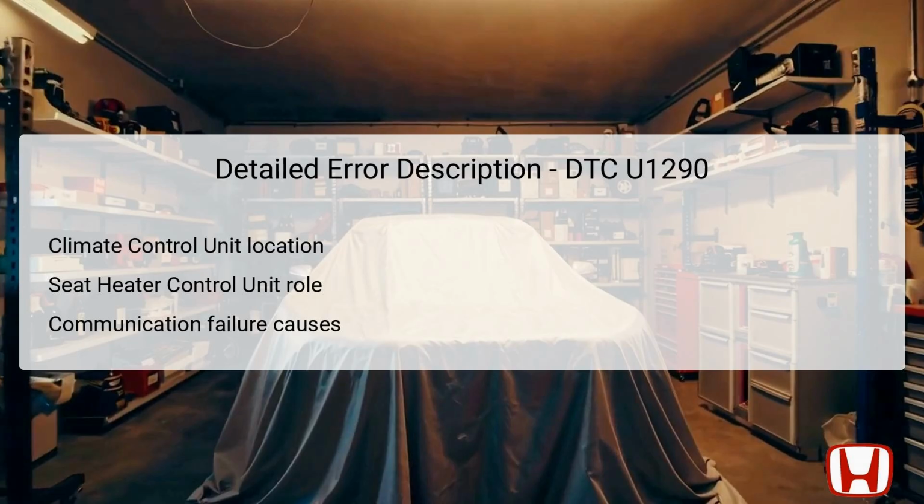Its location is usually within the seat assembly itself, making it less visible compared to the climate control unit. When these two units cannot exchange data, it may indicate a communication breakdown, often caused by wiring issues or power interruptions. Identifying these components helps in targeted diagnostics and repairs, especially focusing on the communication lines and power supply connections between the units.